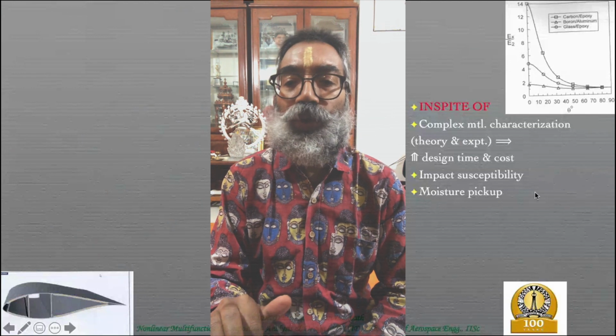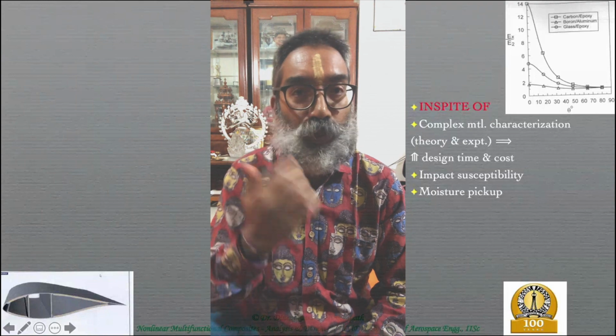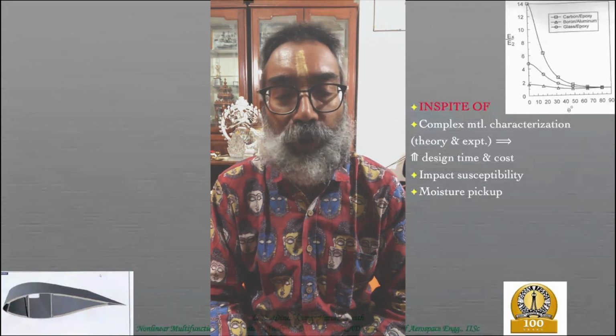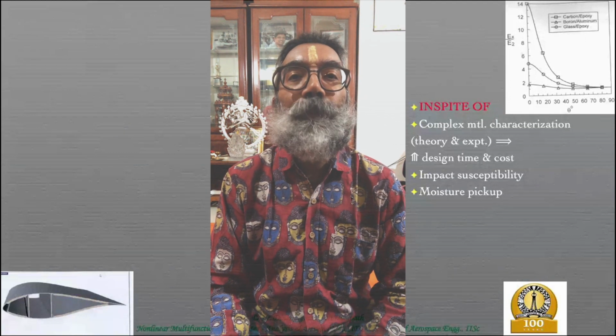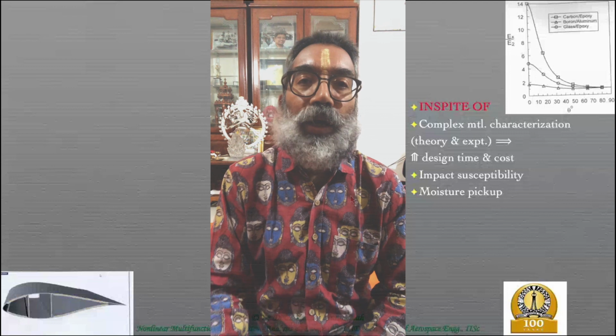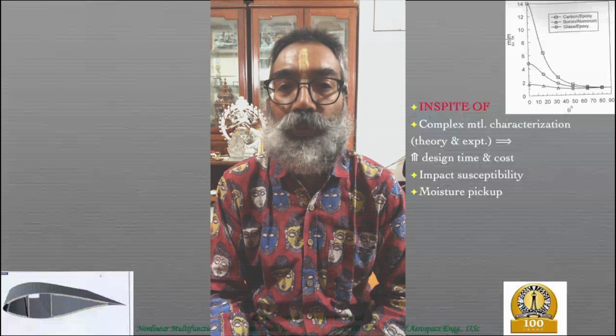The other issue is in terms of hydrothermal stresses, primarily more than the temperature, which may not be much of an issue with polymer matrix composites. It's the moisture. And many of these aircraft might be operating in high humid environments.